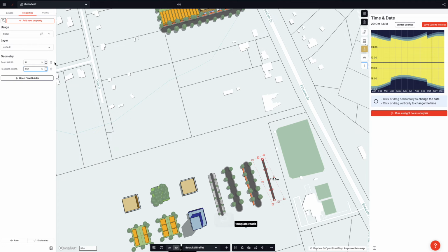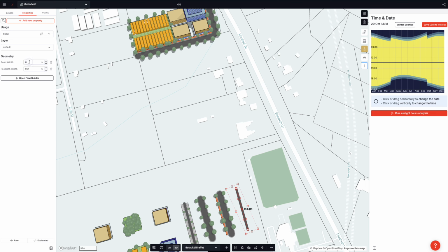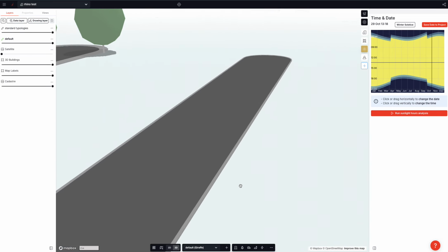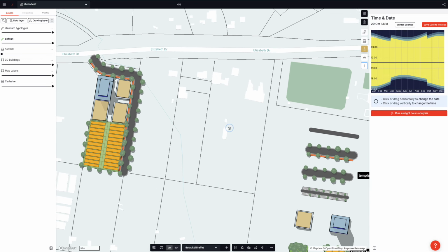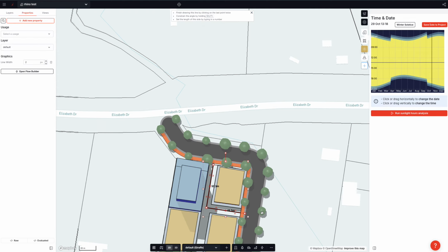So it's like a 0 meter footpath, so 200, but the road width is going to be 9.4, or it should be 9.6, I guess, to add up to 10. There we go. And if I zoom in, that's what it looks like. And so now what I'll do, that's add it to the templates, and I'll add it like this, and then I'm going to hit Y.